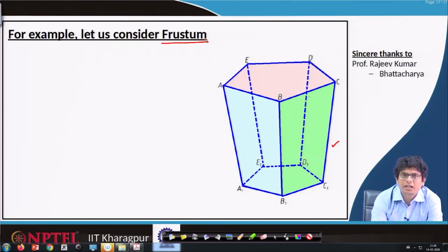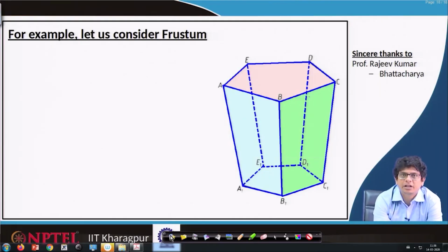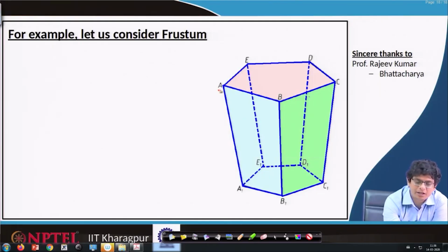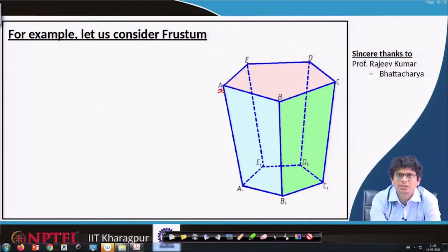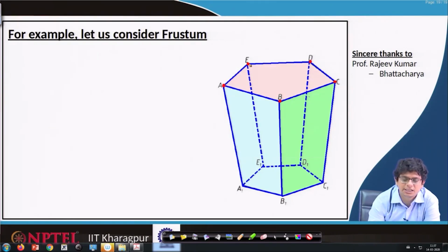So, when we are looking at that, naturally in any engineering drawing we have to represent by letters. Our standard convention is that these 3-dimensional objects we show by capital letters and projections by small letters. So, let us call the parts A, B, C, D, E. Through these edges these lines are passing.